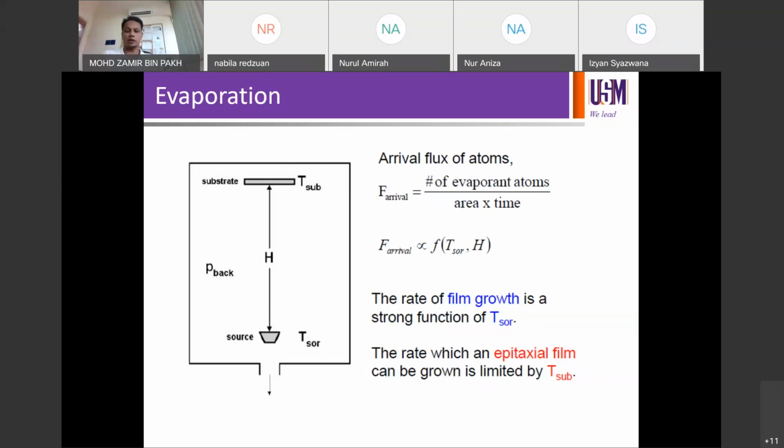So during my PhD, I used electron beam evaporation to do the deposition process. And I did the deposition of a silicon film, about 10 micron thick, on a glass substrate. So that's done on an e-beam evaporation system. So it can be done on silicon as well. But the common precursor materials used for evaporation are usually metals.